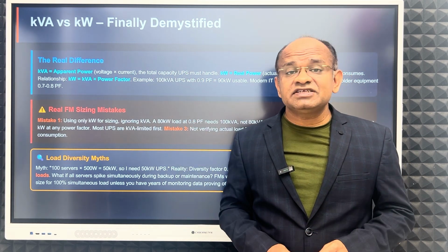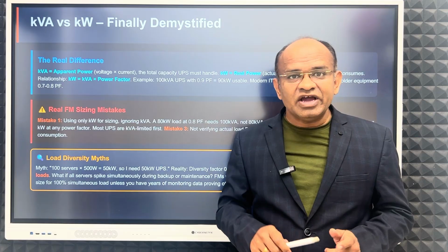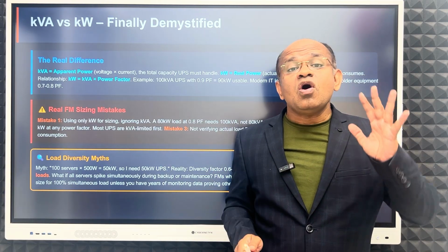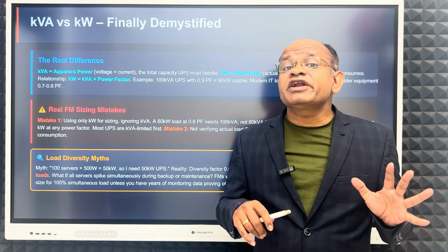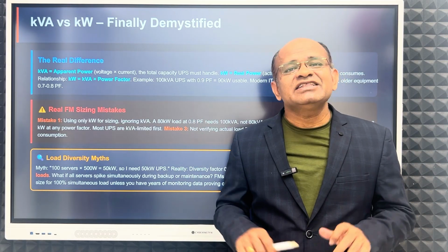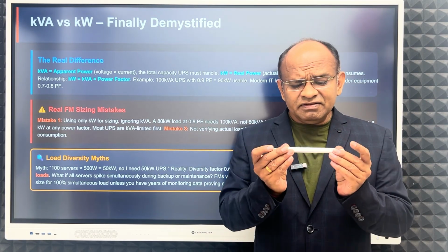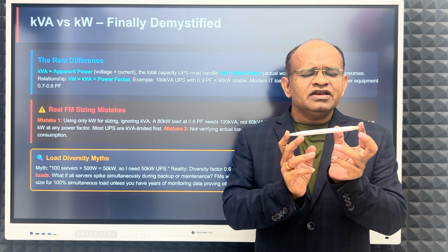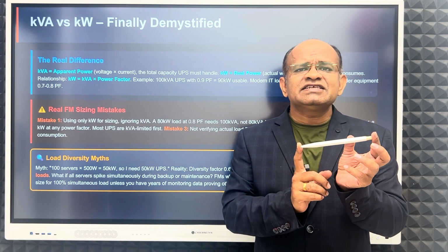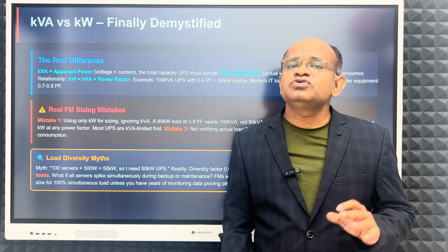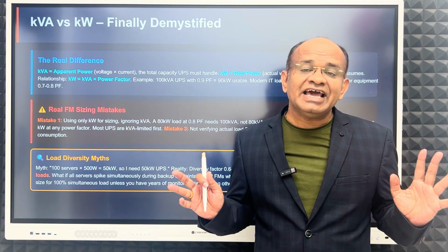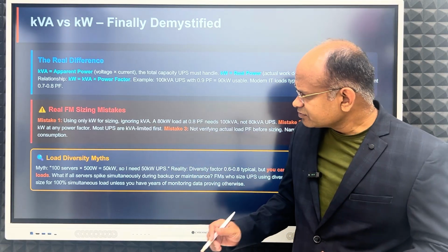So this is diversity. I will be using only air conditioning while I am taking rest, and the light I will not be using. So all the loads will not be working all the time. That is diversity. Let's say 100 is our full load, then all the time you will find 50, 60 or 70% load working. The other loads are taking rest because they are not used. They are connected load.